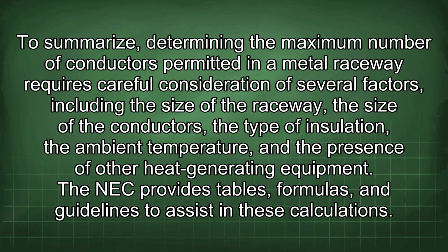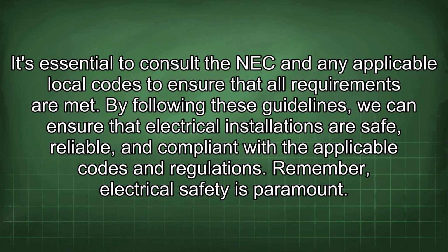To summarize, determining the maximum number of conductors permitted in a metal raceway requires careful consideration of several factors, including the size of the raceway, the size of the conductors, the type of insulation, the ambient temperature, and the presence of other heat-generating equipment. The NEC provides tables, formulas, and guidelines to assist in these calculations. It's essential to consult the NEC and any applicable local codes to ensure that all requirements are met.